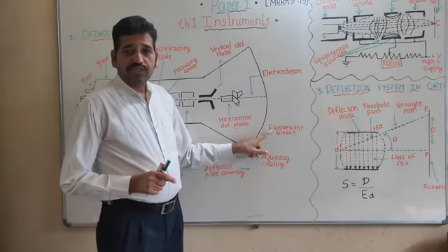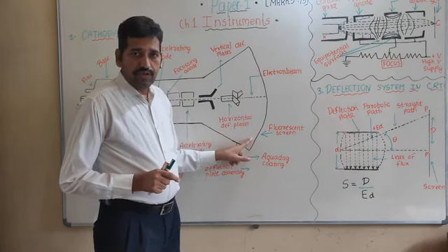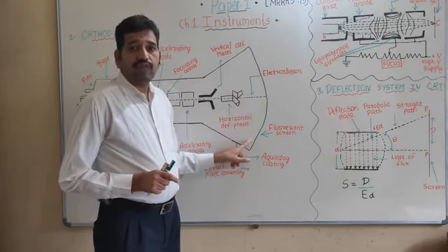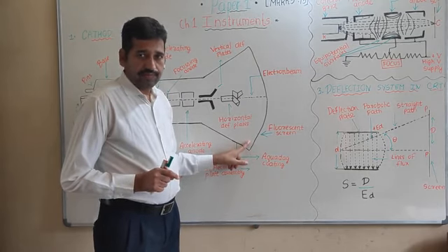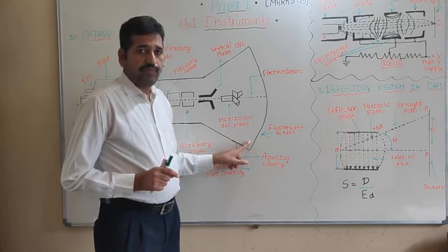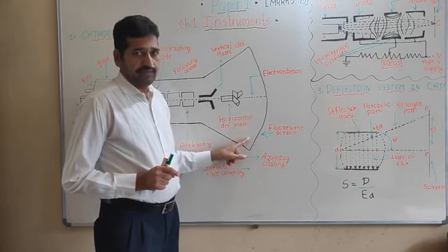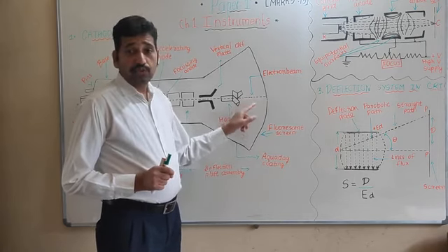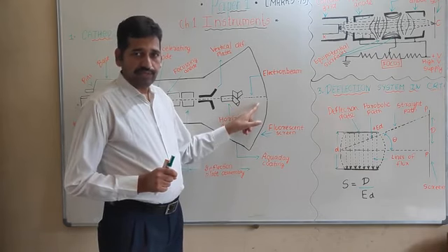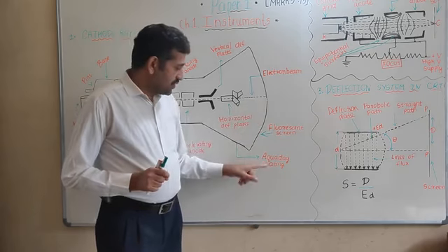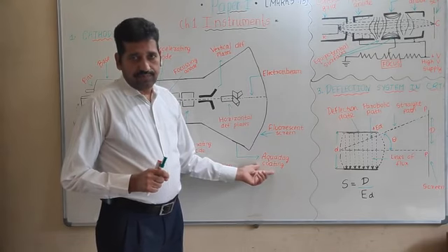Now, the fluorescent screen. It is a thick glass tube which is internally coated by phosphor. This phosphor is an alloy material made up of metal, non-metal, or some minute mixture of radioactive material. It has a tendency to show light when high velocity electrons bombard onto it. Now last is the aquadag coating. The aquadag coating is a graphite coating.